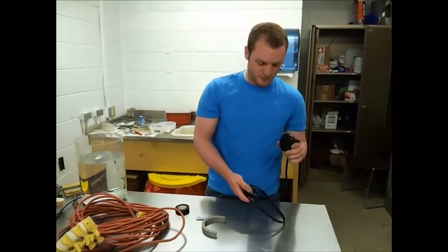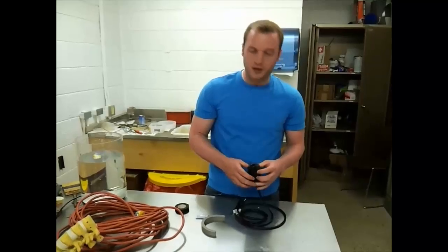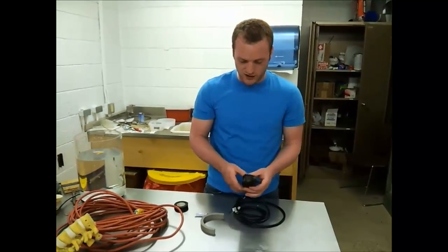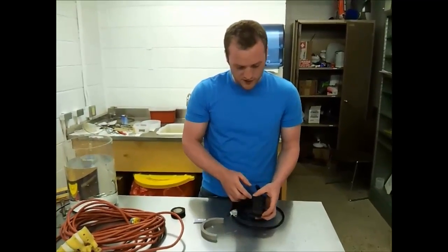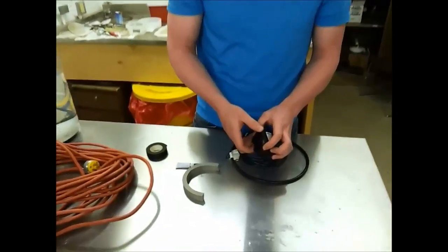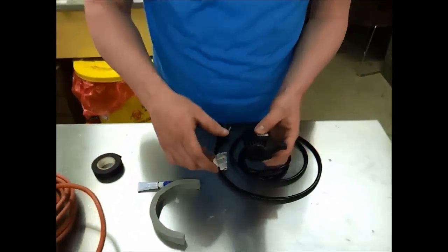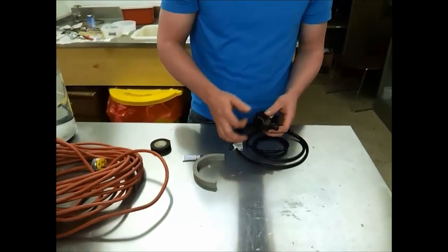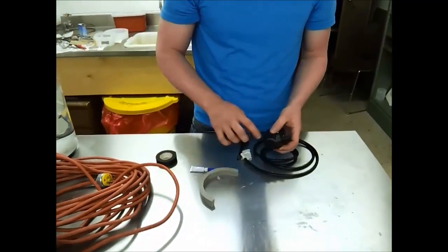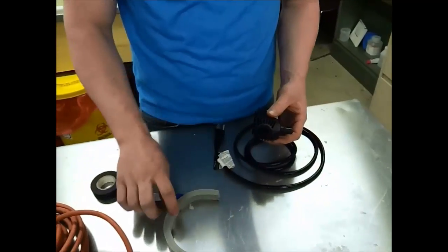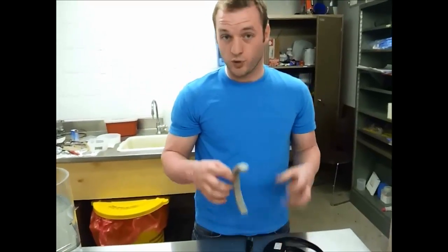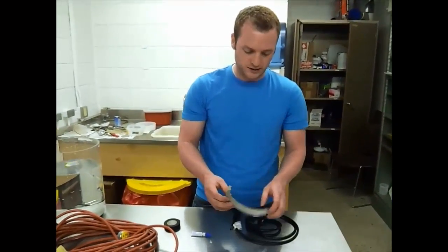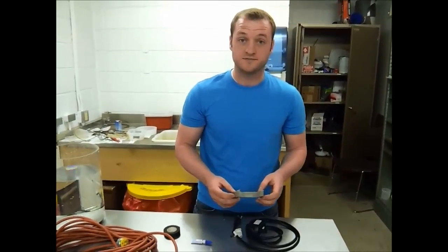So start out with your sump pump, and this is a smart pond sump pump. What you're going to need to do is direct the intake. So there's a couple of slots here and here that we're going to cover up with some electrical tape. See that here. And then for this side, this is where the main intake is. We're going to cover these things on the side here with this door weather sealant. It does 2 things. It directs the flow, but it also gives a little bit of cushion to the pump because it's going to be dragging on the bottom of the pond.